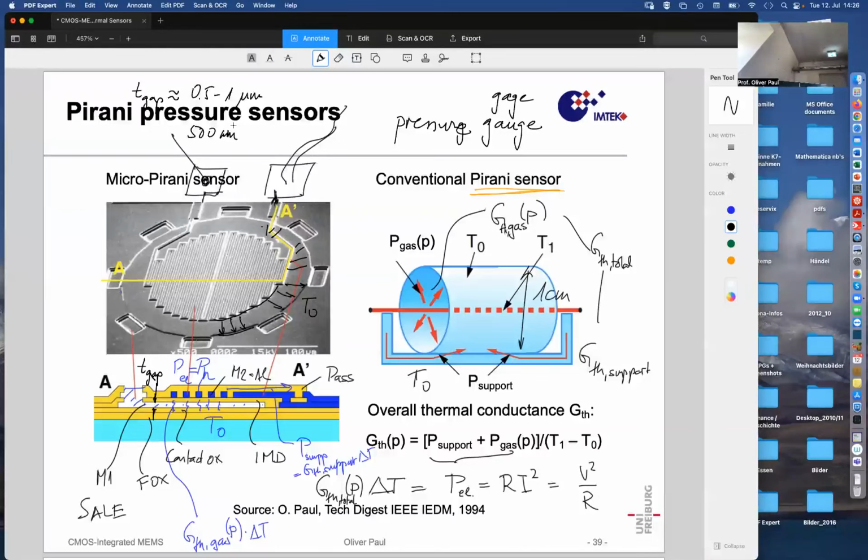So at that point, the mean free path will be increased from 100 nanometers at atmospheric pressure to 500 nanometers at this reduced pressure. So at 1/5 of an atmosphere, we'll have the transition from continuum thermal conduction to collision-less molecular transport mediated thermal conduction.